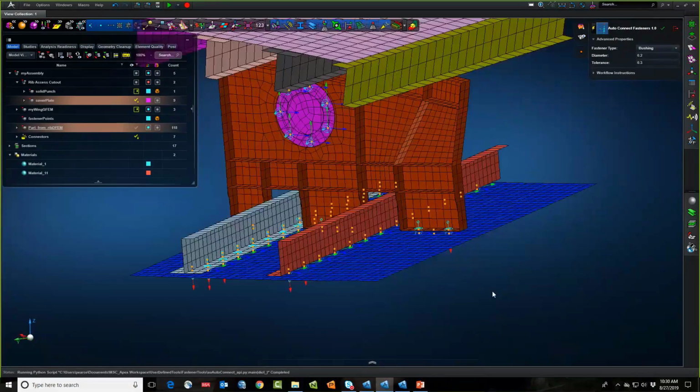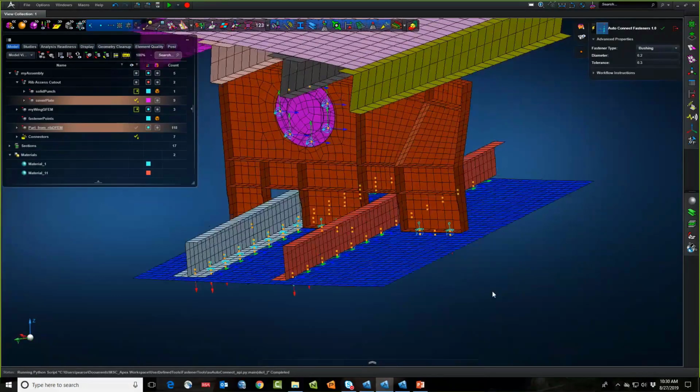All right. So the point was I imported an orphan mesh, and I actually turned it into geometry, surface geometry in this case. And I actually made quite a few modifications to this using the geometry tools that are in Apex, remeshed it, totally repurposed it, totally redesigned it. Started with an existing mesh that represented behavior, modified that, and I now feel I have a more apples-to-apples comparison with the previous design because I've inherited the behavior that was part of the orphan mesh.